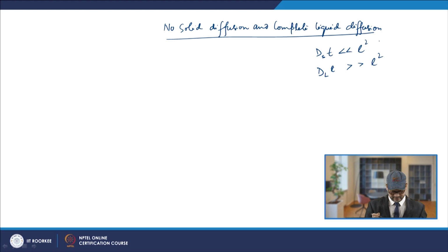In this case the solute cannot diffuse back into the solid, so it will be rejecting the solute, and that has to go into the liquid. So, in the liquid, the concentration of the solute will go on increasing. And since the solid has to come out from this liquid only, its concentration will go on increasing, so the solid which is formed later on will also have increasing concentration. So that way you do not have uniform composition of the solid which is formed.